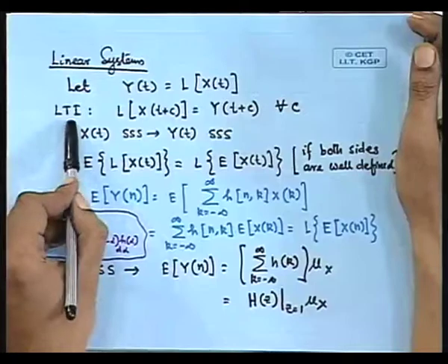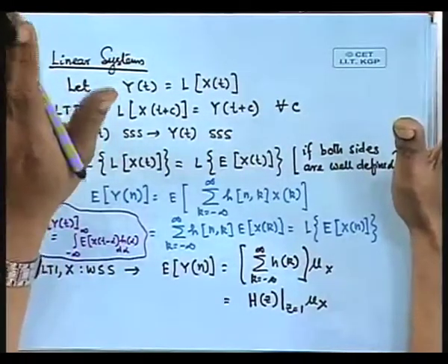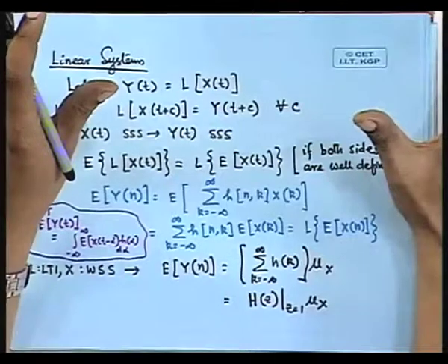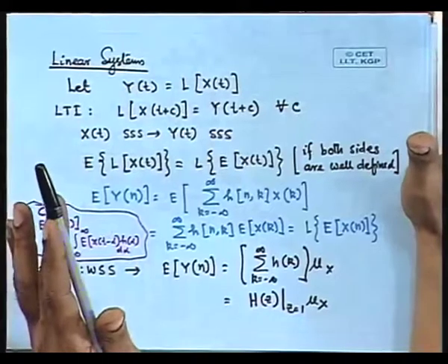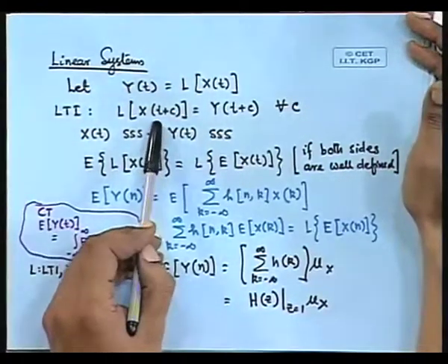And we are treating a simple case, because otherwise the complexity will blow up on our face. So we are thinking of a linear time invariant system. Which means that the characteristic, let us say the gain of the system that we are talking of, does not change with time. So if you apply a signal now and you get a response now, you will get the same response if you apply the input 2 seconds later, 2 seconds later. So the gain does not change with time. So the system characteristic does not change with time, right? So we will generally be talking about linear time invariant operators.